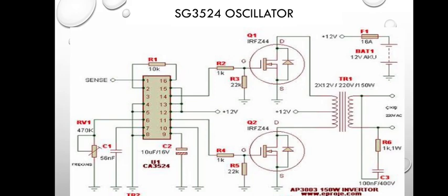Now the pin 10, if you notice, it is connected to ground, but we are not going to connect anything to this pin 10. Yes, don't connect it to ground. We will be connecting it to our battery low circuit, and that will be available in the next video. But for testing, for the sake of those that will want to test it after watching this video, you can just connect pin 10 to ground.